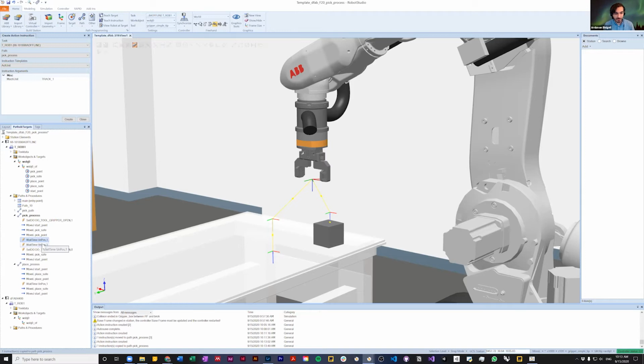So I'm not going to go through the whole workflow. And then sandwich this set DO gripper open between two wait commands, which means that the robot gets here, waits for a fraction of a second or 1 second to make sure everything is settling down, then closes the gripper and waits 1 second until the whole gripper gets closed, and then starts moving back. So this is really important. This sandwich here, like wait, action, wait, is really important for your workflow.